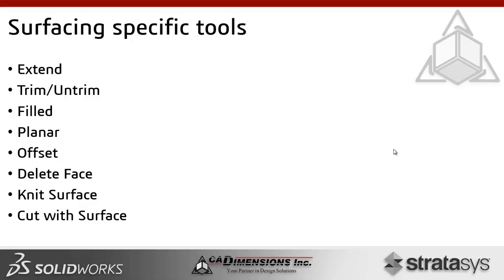We'll also talk about offsetting surfaces, and offsetting goes along with copying the face. I'm also going to talk about delete face. Now, it's not really a surfacing tool, but it does lend itself well to working with surfaces. We're going to be talking about knit surface and then cut with surface.